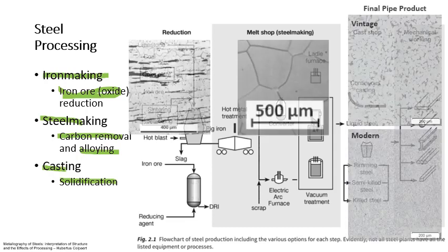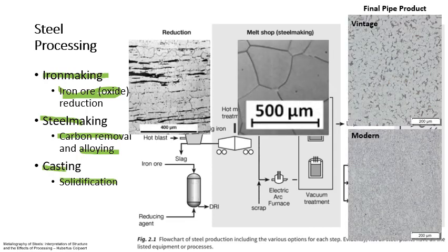If we look at what we did to the microstructure through this process and how we added value, firstly, in the liquid iron, there would have been a lot of those carbides due to the high carbon content, oxides, silicates, and other inclusions, and a generally dirty product that would have been low strength, low toughness. So we turned that into steel by removing a lot of those impurities, reducing the carbon, and we made pretty much pure iron before our secondary refining. But that would have been a really soft product, pure, but really, really soft and low strength.